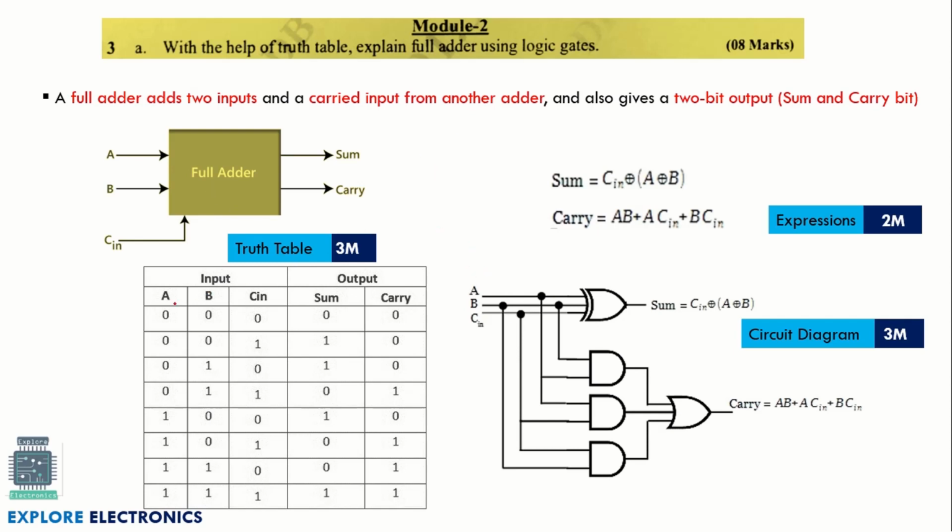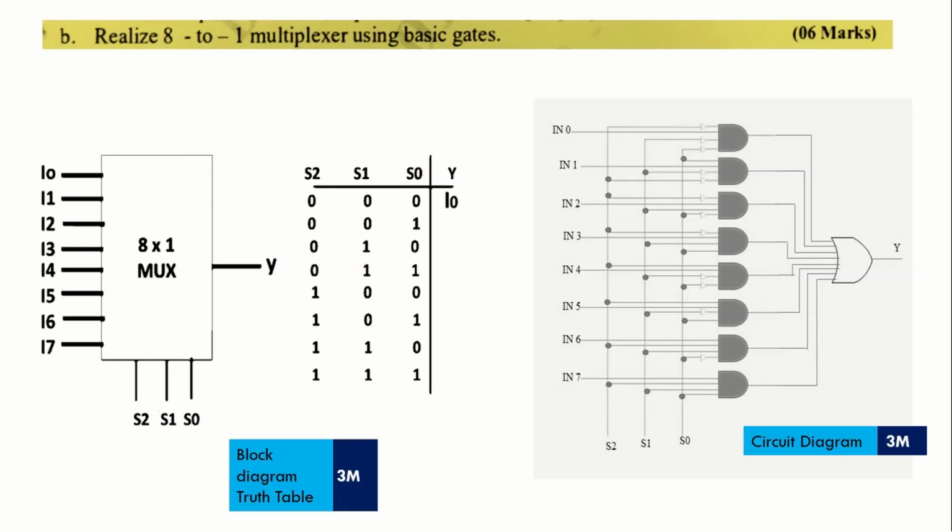So here the full adder by taking A, B, C, sum and carry. So you need to use the suitable same variable names here also while writing the expression. By writing S here, by writing sum here, it will not give meaning. So you need to take care of those things. If you declare it as sum as output here, here also you need to write it as sum, here also you need to write it as sum, and carry. Sometimes you are going to write it as C out. Don't make the mistakes in writing carry once and C out once like that. So brief explanation about the full adder is also required here, and you can explain in 1 or 2 lines like this.